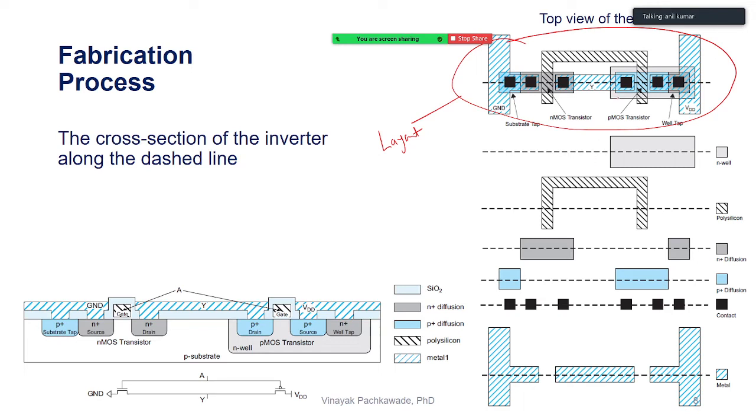Yes, sir. So in the library, most of the times, for instance if you are an analog designer designing an amplifier circuit, it will be ready-made there: the cell, the layout for the PMOS transistor and the NMOS transistor. So you will directly pick up these two masks from the library, and the only thing you need to do is make the input-output connections.